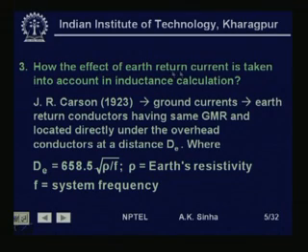The third question was how the effect of earth return current is taken into account in inductance calculation. Well, J.R. Carson in his paper in 1923 said that the earth return currents can be taken into account by means of considering earth return conductors. That is, we assume imaginary conductors which are placed below the ground.